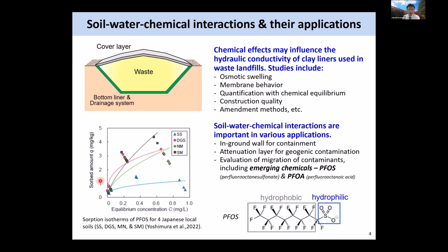One more question. The blue, because we have 4 types of soils here. The blue would be the sandy, gravelly, cohesionless. Yes. So the finer the material, the more absorption of the contamination. So the red line would be some sort of clay. Red line is the higher line.